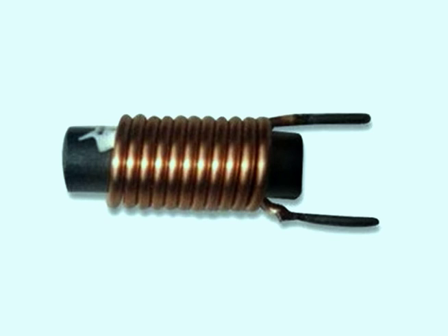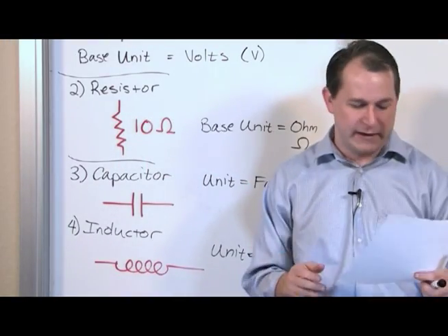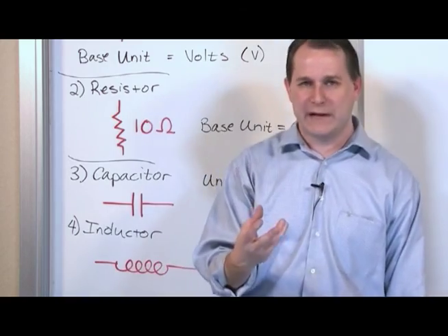If you put metal in there, of course you have an insulated wire, you don't want it to touch the metal, but it's going to concentrate the magnetic field a little bit more, and change the inductance a little bit, and so on. So there are different ways to construct them, but ultimately you're just trying to make that inductance a specific value for your application.